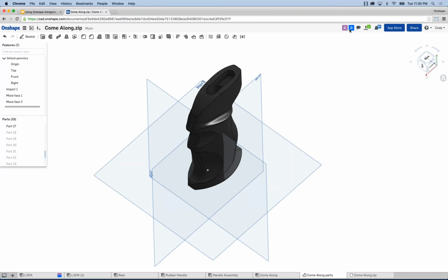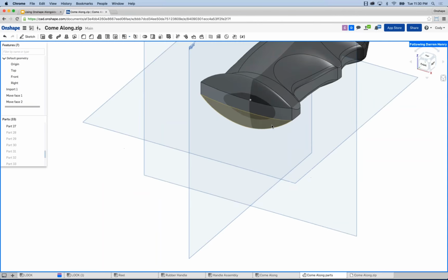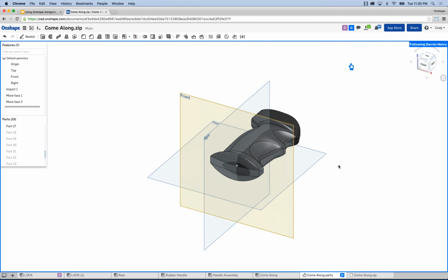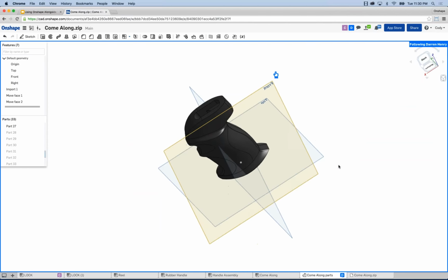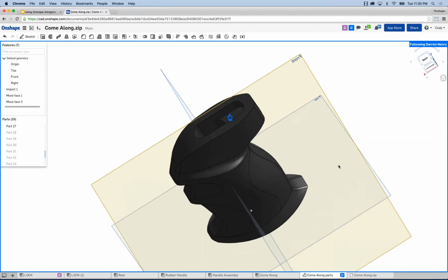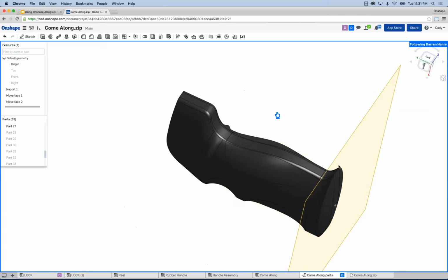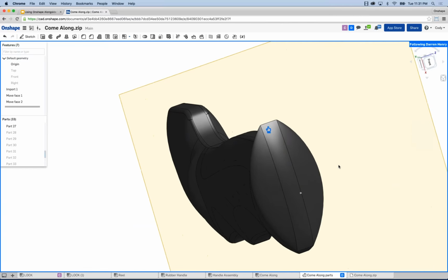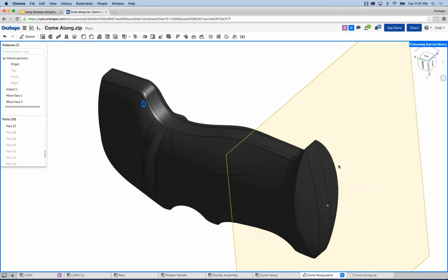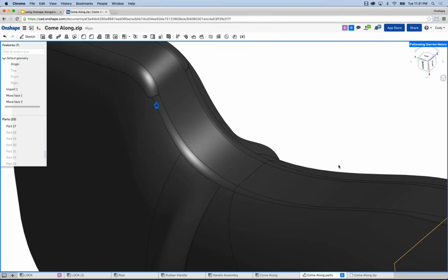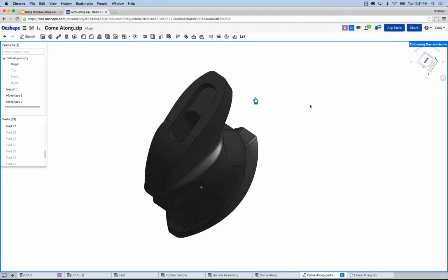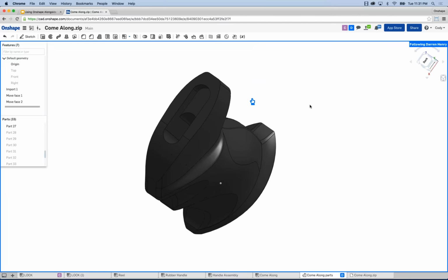And if I double click that D, the icon for his social cue, I'm now looking at his screen in real time. And the neat thing about this is he can point out issues. So he can rotate the model around. So, okay, this is the issue that I'm referring to. This is the pocket that wasn't deep enough, for example. And I'm not sending screenshots back and forth. This is not this big, long hassle to communicate what we're talking about. He can point to the exact face or the exact edge that he's having an issue with. And there's no translation issues here, right? It's very easy for me to understand. So that's follow mode. And again, you just simply double click their social cue in the top right corner.